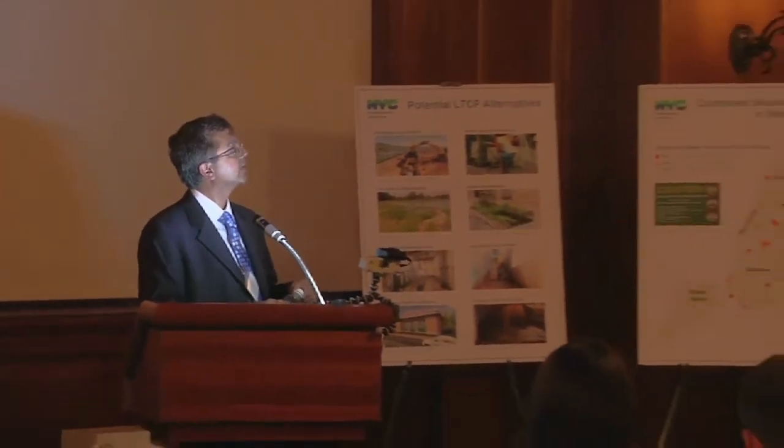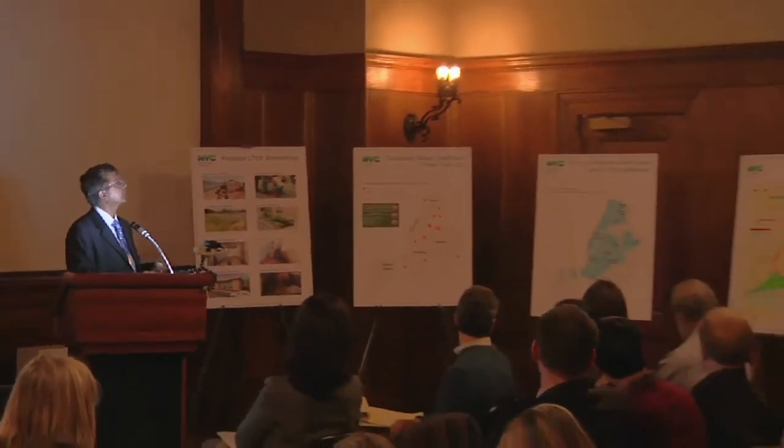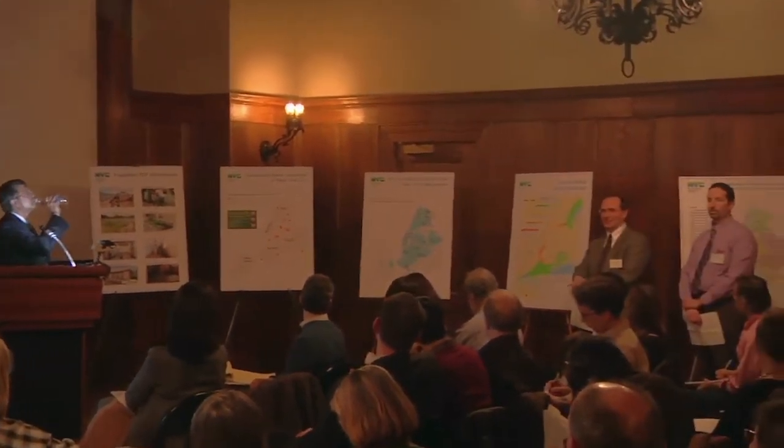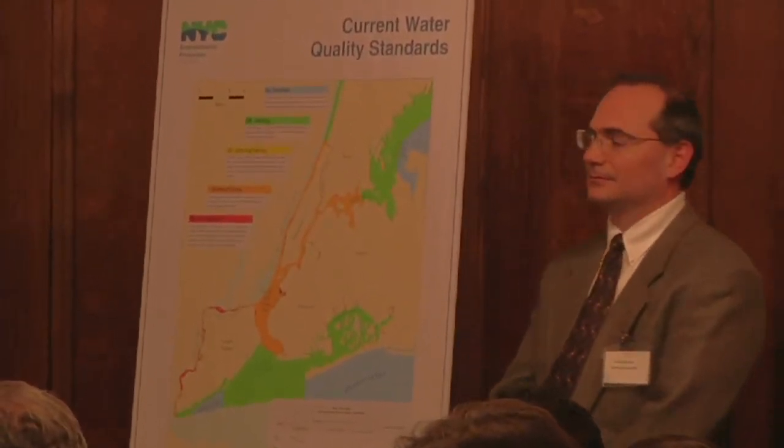Tom, do you want to comment on the floatables modeling process? We don't see floatables as an issue of obstructing the flow in the sewer system. I think you would see floatables obstructing flows more on the streets, where they end up on the catch basin grates, and then the flow can't get down to the catch basin, so it skips and goes to the next catch basin.